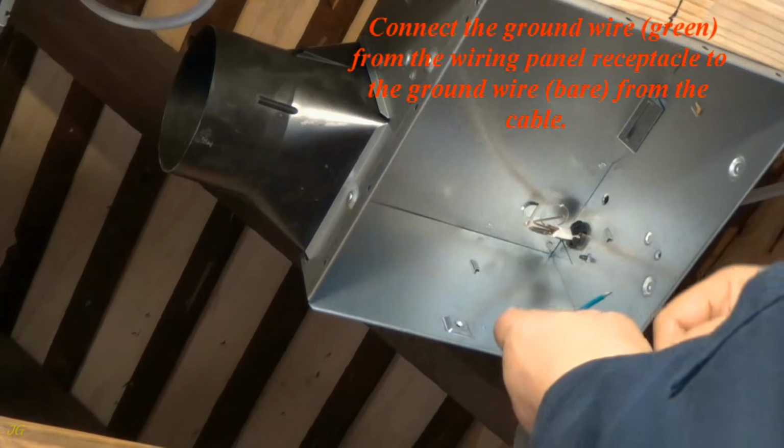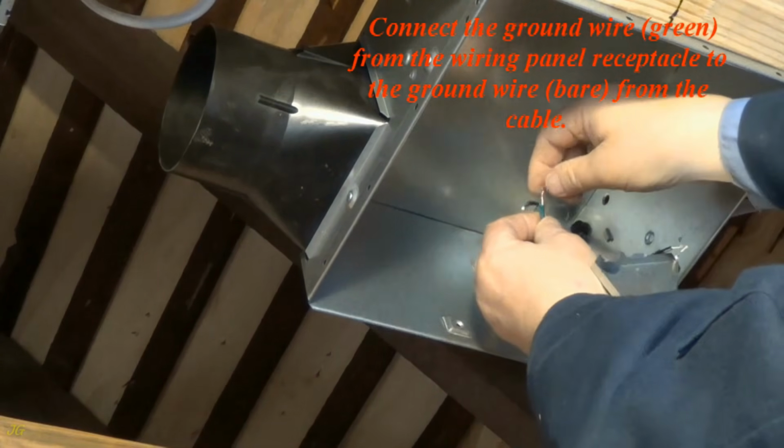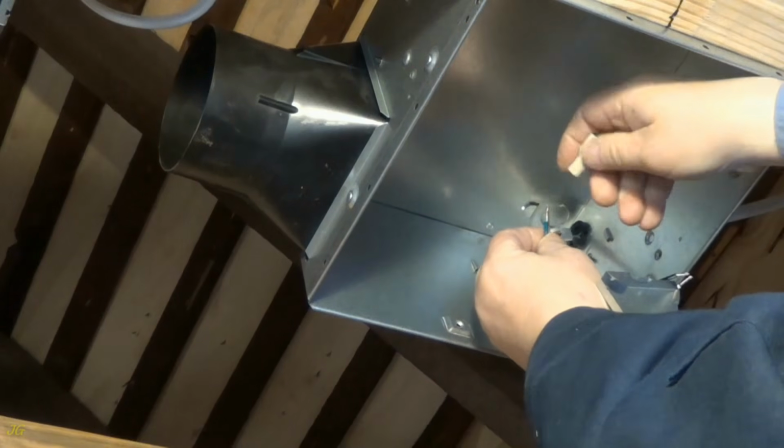Connect the ground wire, green, from the wiring panel receptacle to the ground wire, bare, from the cable.